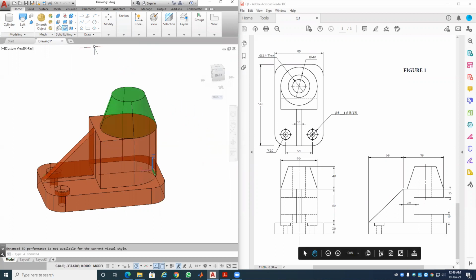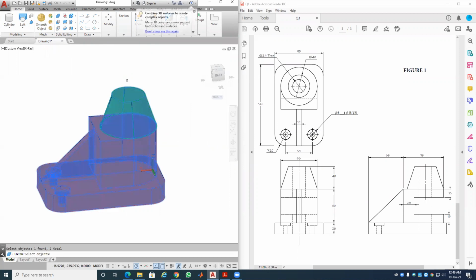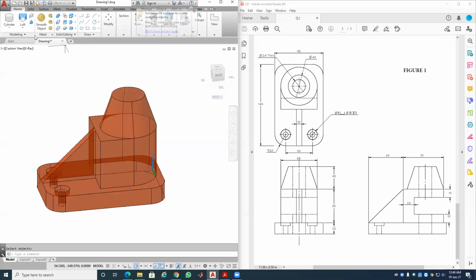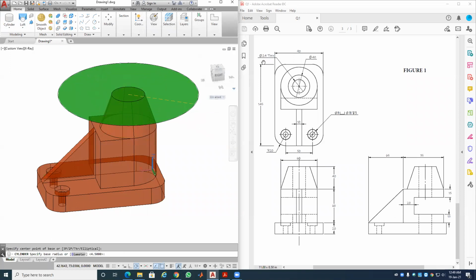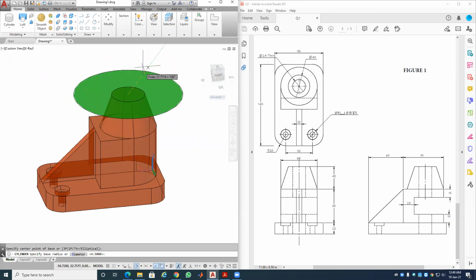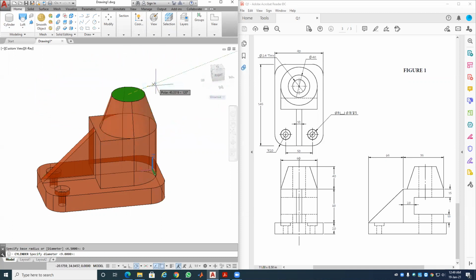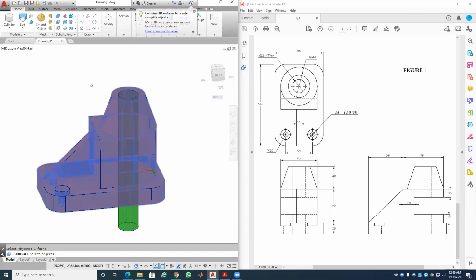So here is a loft, so you learn something about that, and then from there, this is the easiest one left to do, or maybe the next one is this one. So I'm gonna join this first. So join this and this together, and then go from this top, and you know the diameter is 24. Go with the diameter 24 and go all the way down through and choose this one.